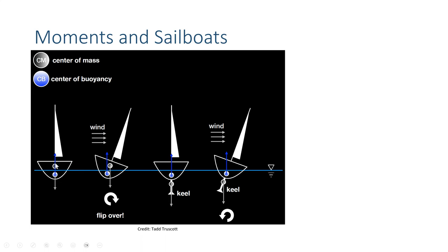And so we've got the center of mass, and so that's pulling our boat down toward the center of the earth. And then we've got our buoyancy force, which we calculated out is all of the volume of the water being displaced here because of the boat. That generates a buoyancy force, which is pushing our boat upward. And so the center of buoyancy is kind of like the center of mass. We've got a single point here where we could resolve all of that force that is generated by the water pushing against the hull of the boat. It's pushing it in the upward direction.